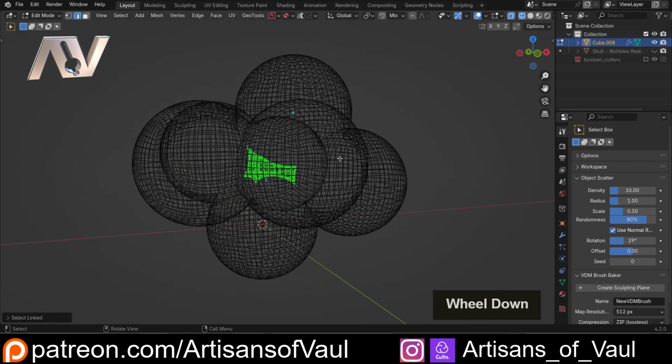I should also add that 3D Builder, which is a massive favourite program of mine for fixing 3D printable objects, can on occasion cause these problems when trying to fix objects with a lot of internal overlapping faces, which is why I always recommend using Blender to boolean objects together and then using 3D Builder just to test them, not as your main source of combining objects.